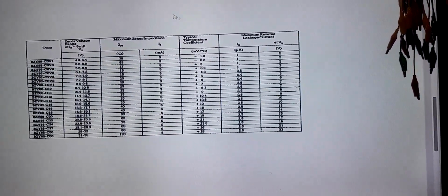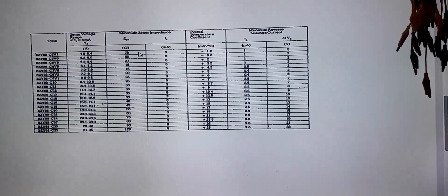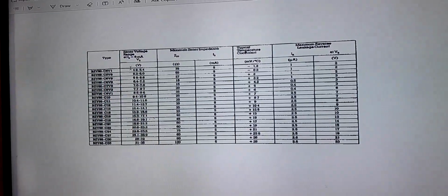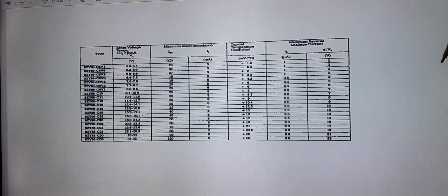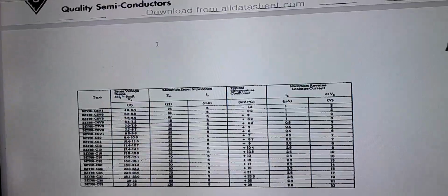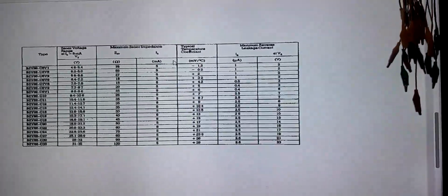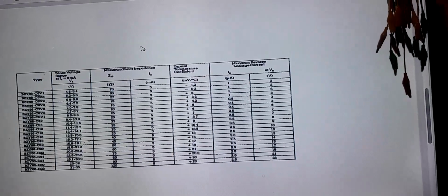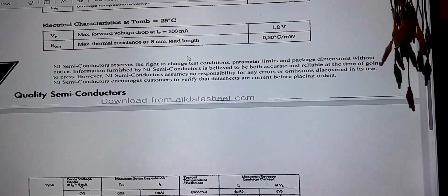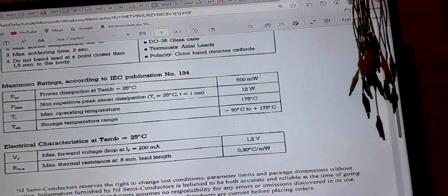Actually, I wonder about the maximum Zener impedance. Oh yeah, because it also says here the regulation voltage at 8 milliamps. Well, that probably is 5 too. It's just really hard to read the text. But 4.8 to 5.4 volts. So I'd say they're a soft knee Zener, just looking at the specs here. They don't seem to have very hard characteristics, you know, although they are half watt Zeners.